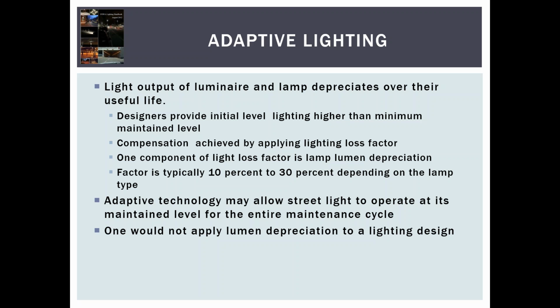Roundabouts. Due to the geometry of roundabouts and the effectiveness of fixed headlights within the roundabout circle, dimming should not be applied to these facilities. And rail crossings. Rail crossing lighting is provided for the detection of trains. It is not related to pedestrian conflict levels. Therefore, reduced lighting in off-peak periods is not recommended.